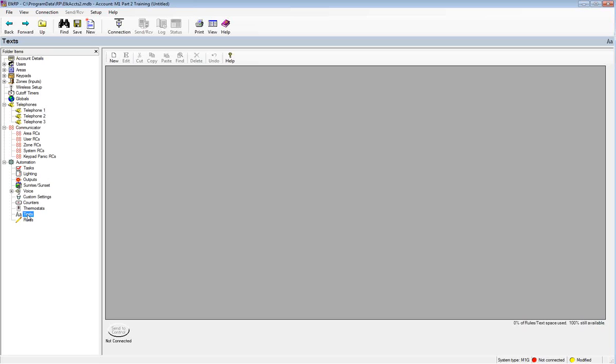This is also the area if we're integrating with a piece of equipment that we're not currently directly integrating with, and that piece of equipment offers their RS-232 protocol. You can write these custom ASCII strings and send them out the M1 to this third-party equipment to do some generic information. It wouldn't be full integration, but in some cases on, off, or a certain set point and so forth is possible using their RS-232 protocol.